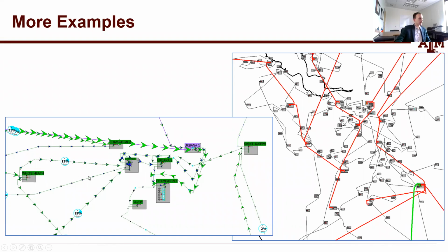And a similar thing, you can see this line right here ended up having this bend added right here so that it's not going straight across this existing substation, this White Heath substation here. So that's kind of the idea of this line routing algorithm. This is not claiming that this is going to give you a perfect one-line diagram straight out of the box, but it's considered a starting point that gives you a good initial diagram that you can then go back, if you want a really high quality diagram, and hand adjust a little bit. And so we do that sometimes, but it's really good.